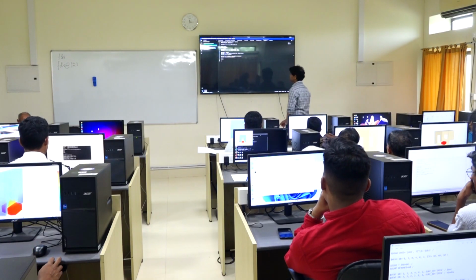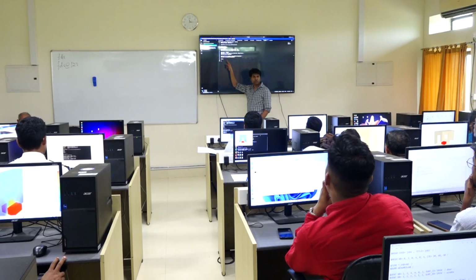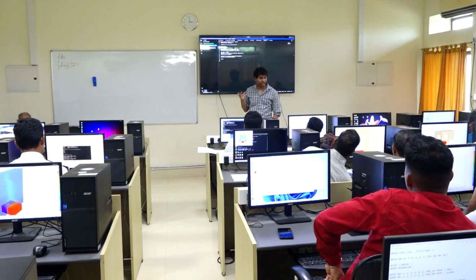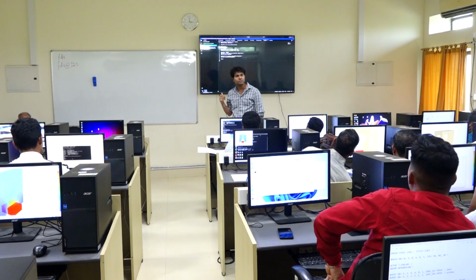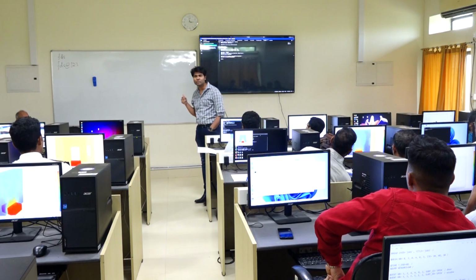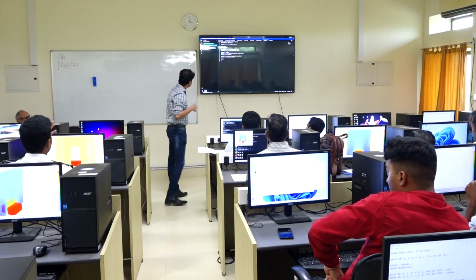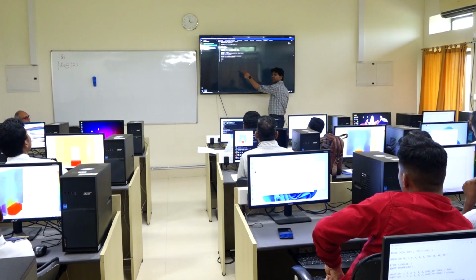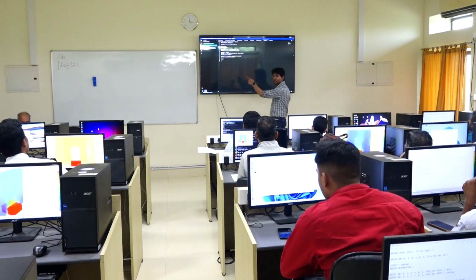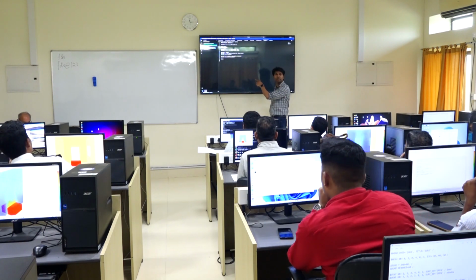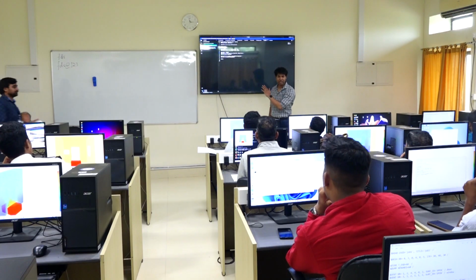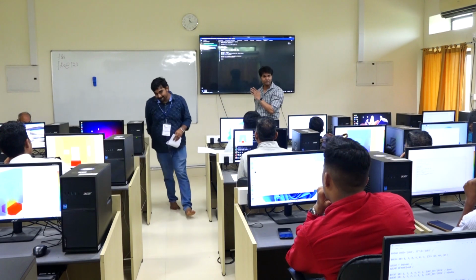Okay? Now let's say if you want to create more slices, then you basically add those in this code. Okay? So let's say if you want to have a slice at x is equal to 2, what will you do? So you will write basically ampersand SLCF PBX is equal to 2, comma, QUANTITY is equal to 'TEMPERATURE'. Yeah, same thing. Are you with me? Any questions? Okay.